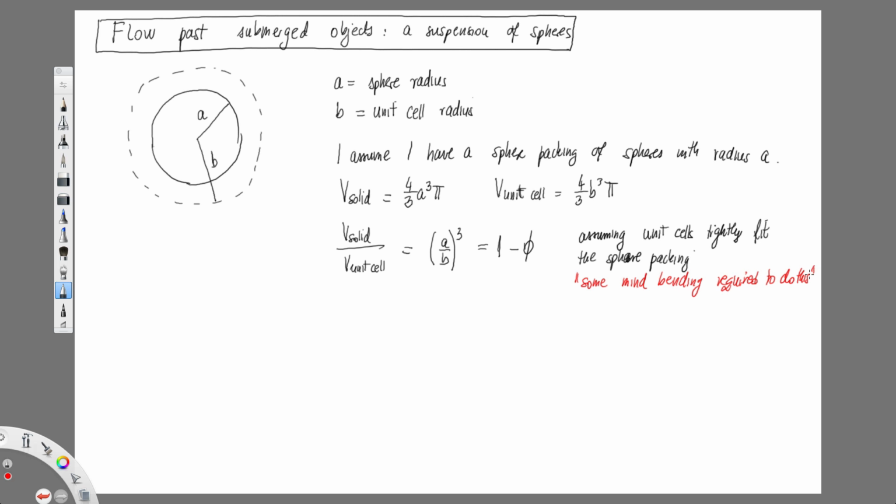What does that mean? That means that I cannot precisely pack things. Again, if I had a sphere packing, I would be able to pack small cubes really neatly. How am I going to pack spheres without having extra volume, right? Yeah, but if you solve this problem, you can translate it to a cube with full porosity. Yes, but if I'm using this, that means that my sphere packing is completely packed with these unit cells, but they're spherical. Okay. So there's some extra space there. But I'm bending it to fit it in. This is just to give me an approximate relationship to porosity, really. And it's not the only crime I'm going to commit here, okay? So this is far from the only crime. So I will actually refer to this as gamma. So basically my gamma cubed is 1 minus V.